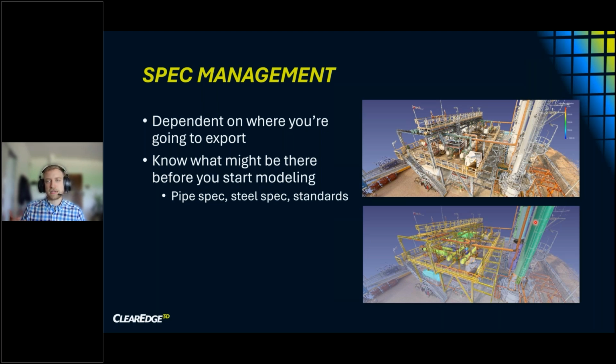And so the actual specs themselves are pretty basic. So piping and structure have the main two catalogs that you're working in. Ducting and cable trays are more just sizes. They're just different size rectangles, basically. So for piping, the key thing, and that's something to really keep in mind, is that at the end of the day, the value of this is what goes into Revit or what goes into Plant 3D or AutoCAD or Inventor or E3D. So we want to keep in mind what we can model in EdgeWise versus what gets into those deliverables, which is really the important question.